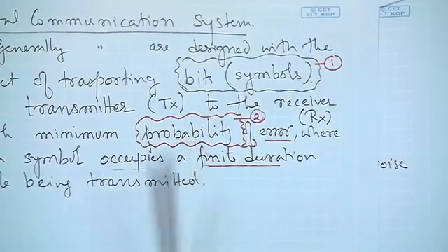So at least you can think that we'll be handling piecewise stationary systems, if nothing else, at least for the time that we are considering the system, its statistical properties do not change with time. Of course there are different definitions of stationarity. There could be strict sense stationarity and wide sense stationarity. We'll be mostly sticking to wide sense stationarity. So at least that again gives us a hint why we need to use this definition of probability, or why we said that probability is a very important term in the study of digital communications.